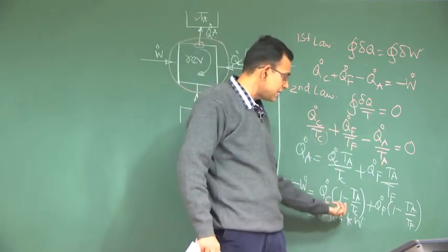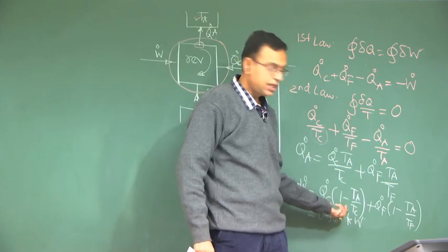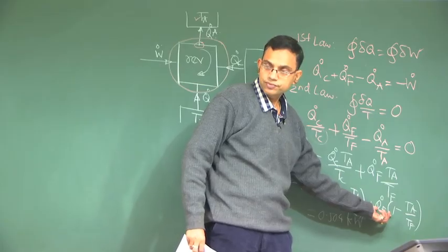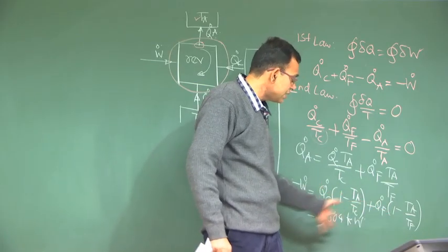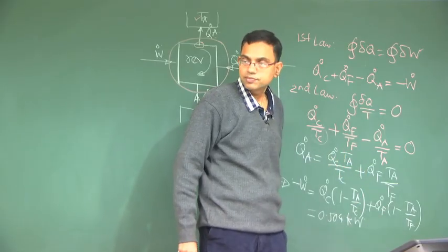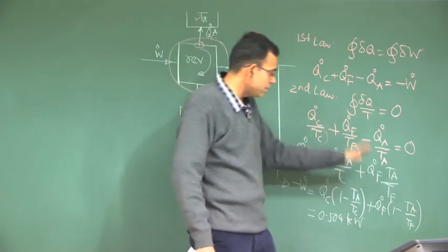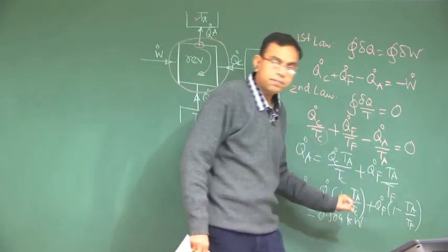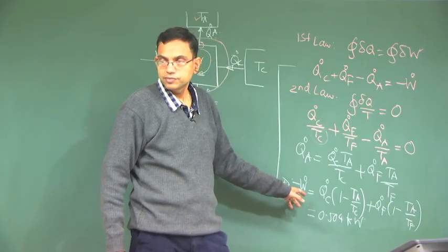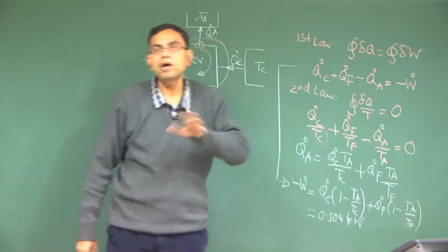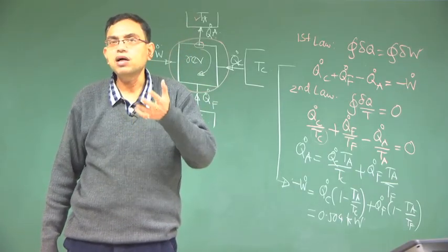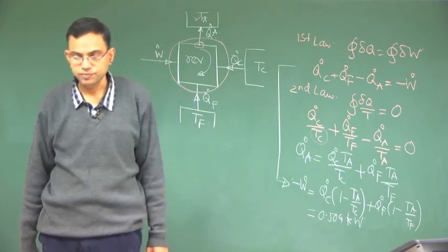and you are trying to find out an expression for the reversible work. So, you can clearly see that this is exergy associated with the heat transfer q dot C, this is exergy associated with the heat transfer q dot F. So, this essentially is an expression that gives the reversible work through exergy balance. Because it is a reversible system, the entire exergy that is supplied is equivalent to the reversible work, there is no irreversibility. Okay. So, you can see that the same problem can be perceived from exergy balance and also directly from a consequence of the first law and the second law.